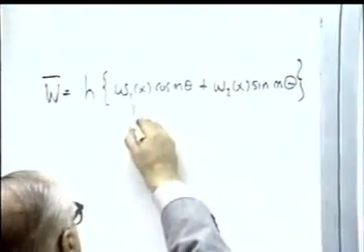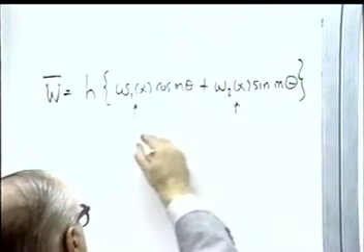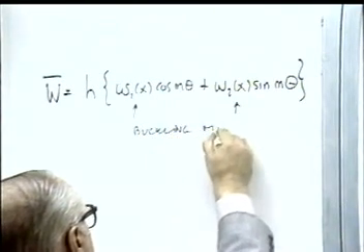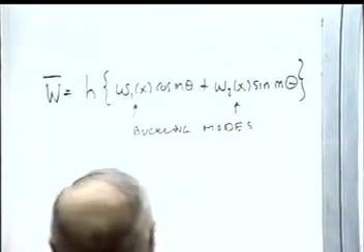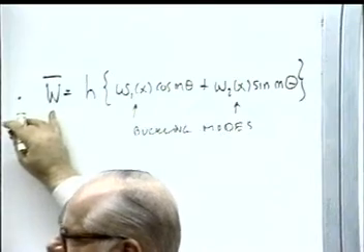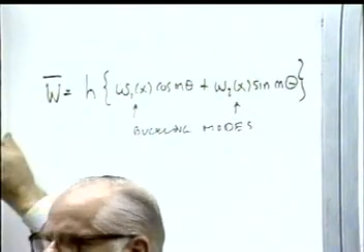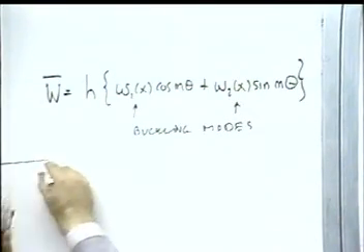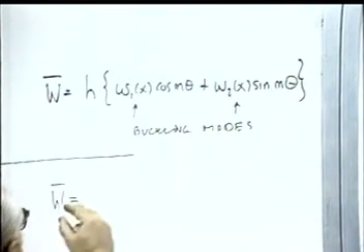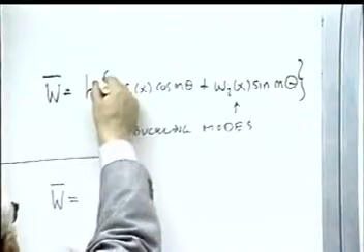So notice these functions here are the buckling modes. So if I use this imperfection and calculate alpha and beta, then the initial imperfection is affine or similar to the buckling mode. Since I have done a lot of measurements, I am also interested, here I am missing an amplitude, right?